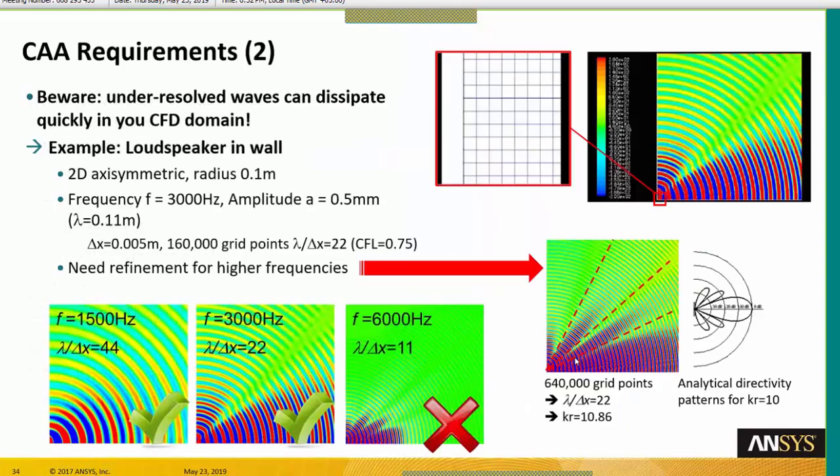Yes, I already talked about this one on session 1, always the same case. With the variation of the wall, the positioning of the wall changing, it is creating some variation of local pressure. It is creating, in fact, an acoustic wave, and you see that when you have poor spatial resolution, with the wavelengths discretized with only 11 points, you are not correctly propagating the acoustic waves. They are damped, in fact, so you need to be extremely careful here.